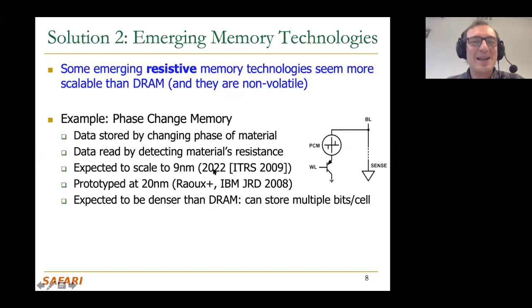It's actually not a bad medium, but rewritable CDs, for example, use some variant of phase change memory. It's very similar in terms of how phase change memory operates. Basically, you have 2 phases, and rewritable CDs take advantage of the fact that these 2 different phases have very different optical reflectivities.